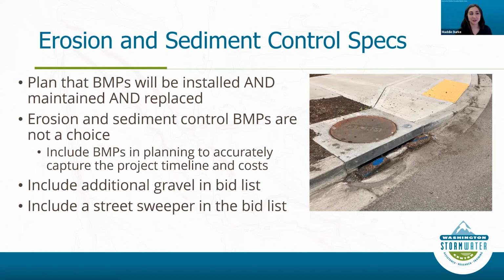Erosion sediment control BMPs are not a choice, so you're doing your contractor a favor if you're including these BMPs in the planning, because this accurately reflects the project timeline and the project costs. You definitely want to include additional gravel in the bid list. Gravel can fill up with sediment and needs to be replaced. You also want to include a street sweeper in the bid list. In the city of Vancouver, we require that a street sweeper comes at the end of every workday.